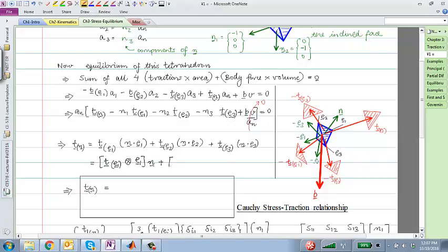Plus T sub E2 dyad with E2 acting on N, plus T sub E3 dyad with E3 acting on N. Do you agree that if this particular expression is just E1 dot with N and in the direction of TE1, which is up here. So the three terms written out here are nothing but expressing the same relationship in the form of a tensor.